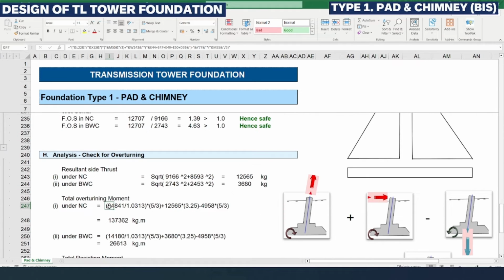So that was done here. Now this force is transferred into the vertical direction instead of inclination with respect to the leg of the structure, and that should be multiplied with 1/3 of the base slab width. We will get the moment due to this uplift.